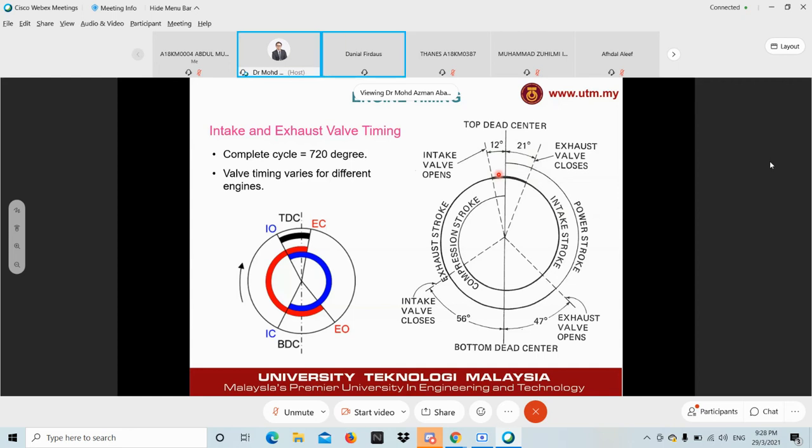And that means in the piston itself, there must be an indent, so that it doesn't hit both the exhaust and intake valve. Yes, correct. Engines with lower compression ratios usually don't have any issues.